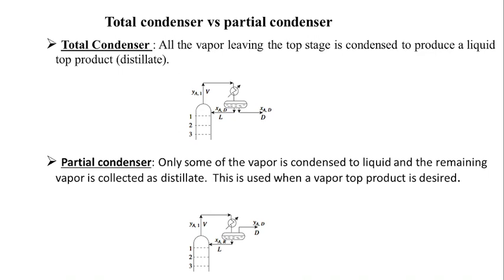In fact, during design you have certain specific design options, and you choose from those. One consideration is that the height of your weir should be sufficient so that all your vapor dispersers remain well submerged. Anything else? We still have a little time.